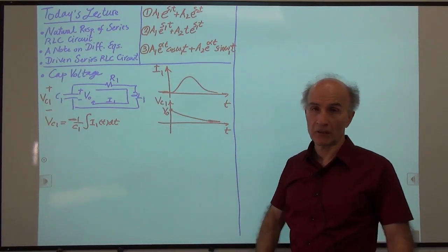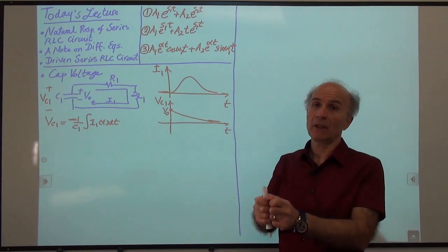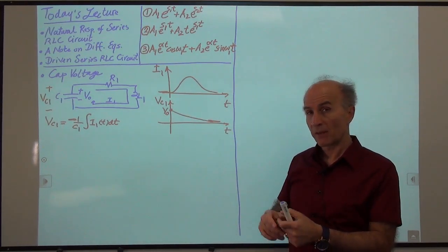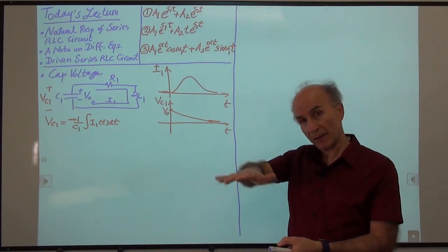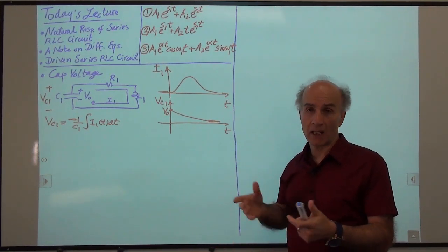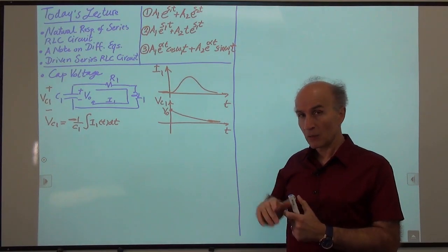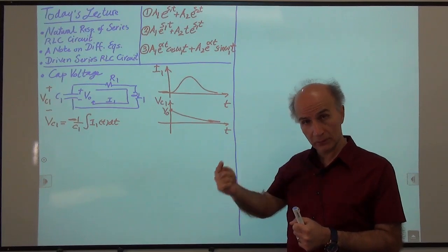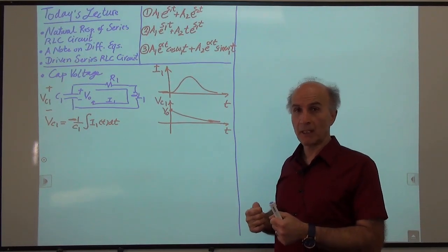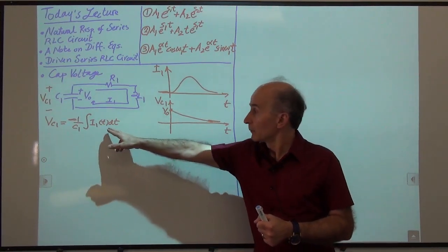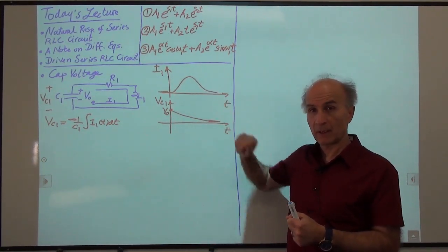Okay? All right, so what this says is integrate the current as a function of time, this current here. Then divide by C1 and then multiply by -1. So flip it upside down. And that will be the voltage across the capacitor. So before we write the equations, let's try to follow this prescription and see, qualitatively speaking, what this will get us if we start from here.